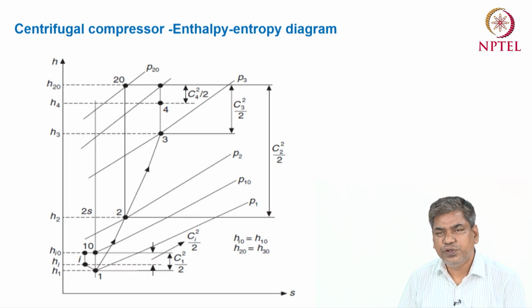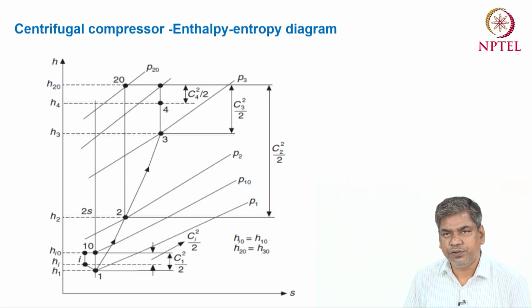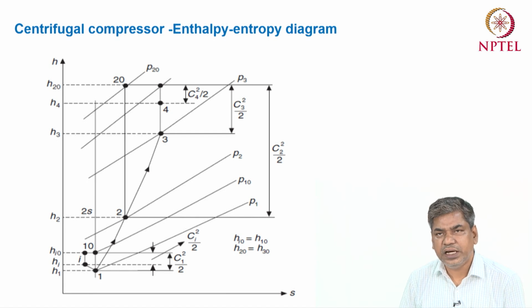Then the refrigerant goes to the rotary vane. State point 1 to 2 is the flow through the rotary vane. During this process, the kinetic energy is the input parameter, so the work for the compressor is given here in terms of the kinetic or rotational energy of the vane. In this case, the enthalpy and kinetic energy both increase due to the work transfer inside the compressor.